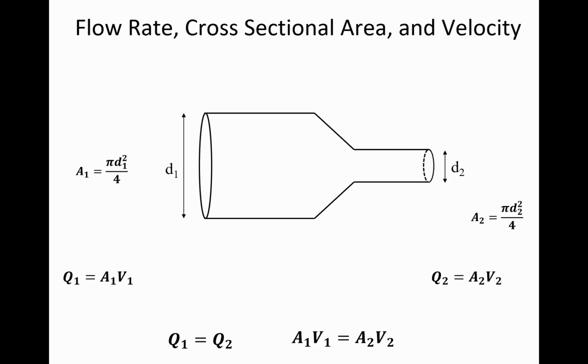And so the jet of water is going to be moving much faster because you put your thumb over the end. So the velocity increases and you can squirt stuff that's further away. So I wanted to point out this continuity relationship because we use it a lot in problems related to Bernoulli's equation. Flow in equals flow out, and specifically A1V1 equals A2V2.